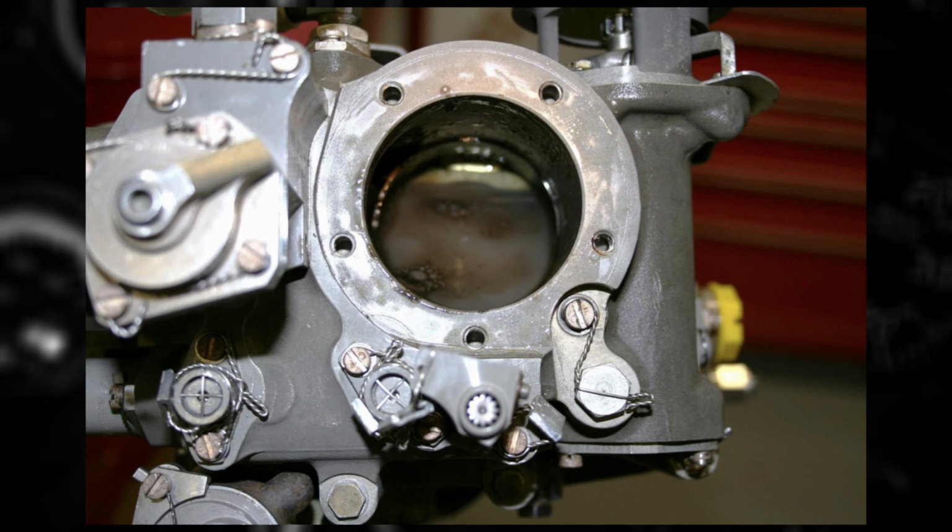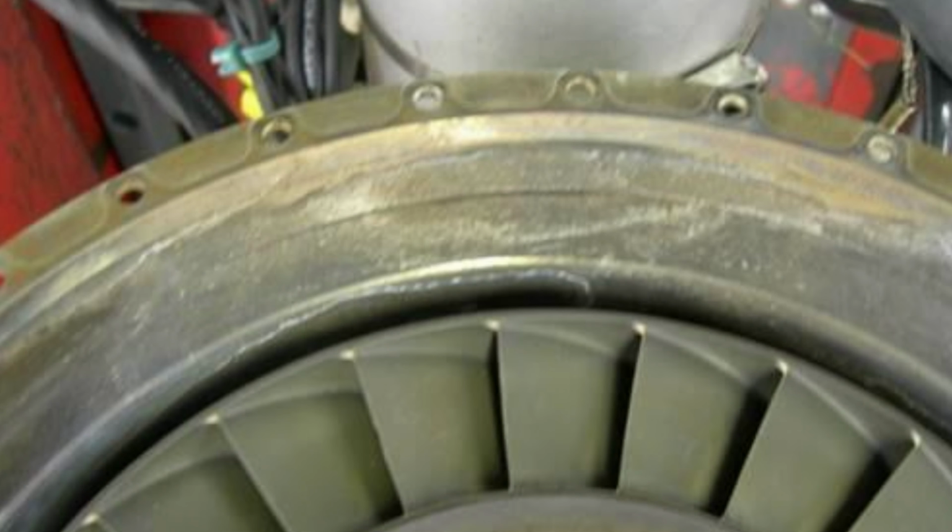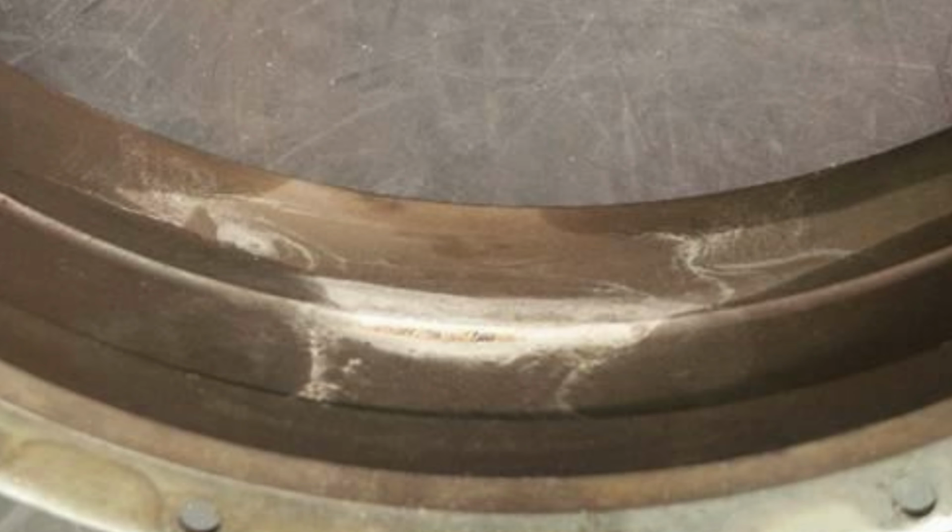And the cleaning chemical is a commercial degreaser. An excessive concentration or volume of the chemical, excessive soaking time, improper rinsing, and skipped or insufficient drying ground run will lead to internal staining, pitting, and corrosion as pictured here.